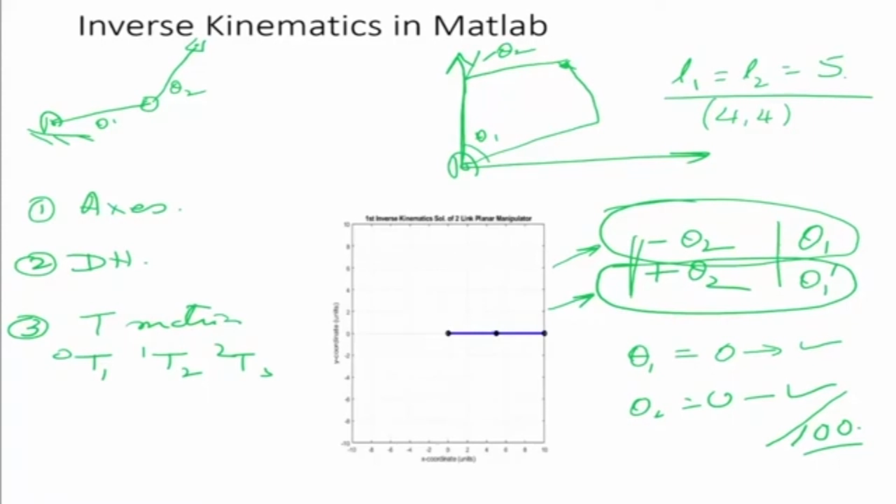You define your axis, make your DH parameter table, find the transformation matrices, multiply each of the matrices, and get joint 1, joint 2, joint 3. Now what are those points? They are the last column of your transformation matrix, the corresponding x and y. So all you have to do is just plot them.